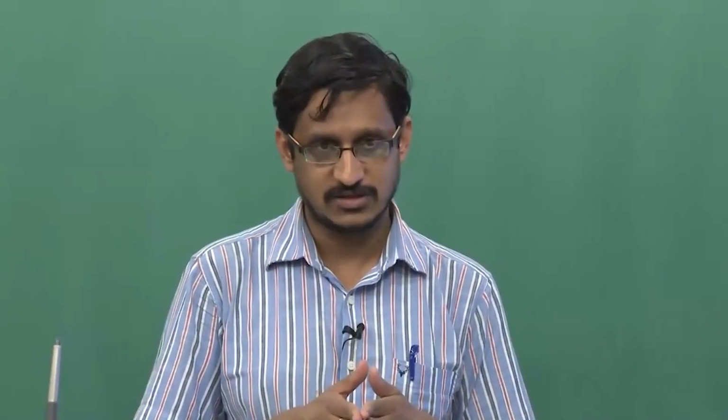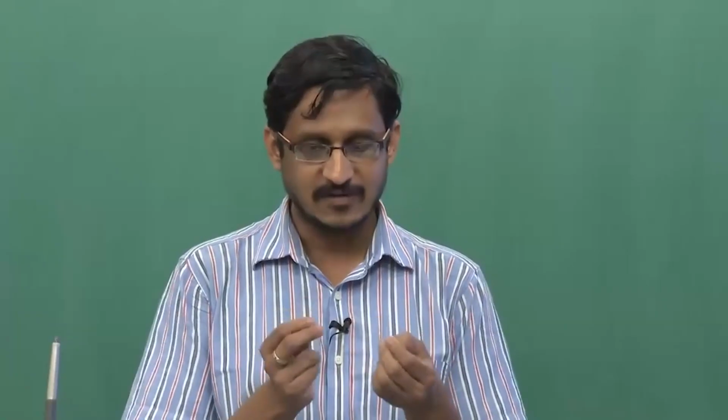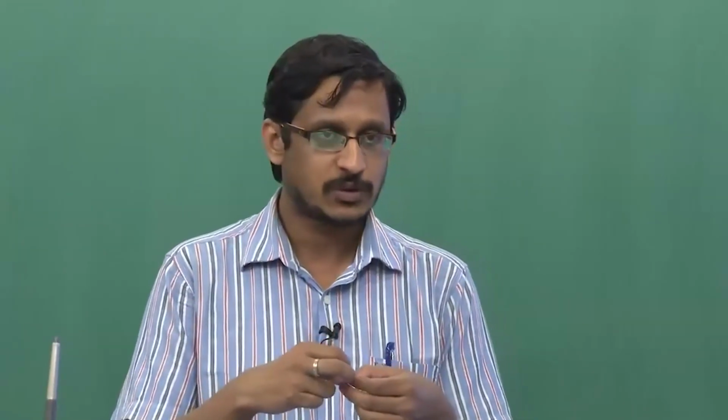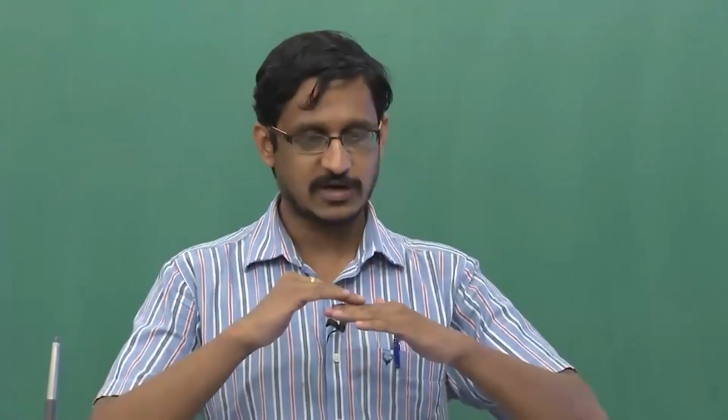So, the phenomenon which resembles this shot of a bullet is called shot noise, and this comes from the fact that the electron hole pairs which are generated are discrete carriers, and they do not constitute a continuous current flow. Actually, current flows in the form of these bullets. Electrons go in the form of a bullet. Sometimes you get one bullet, sometimes two, sometimes three, sometimes 10, sometimes 100. But regardless, it is actually a statistical process. So, there is always a fluctuation about the photocurrent, which will lead to a certain amount of noise.